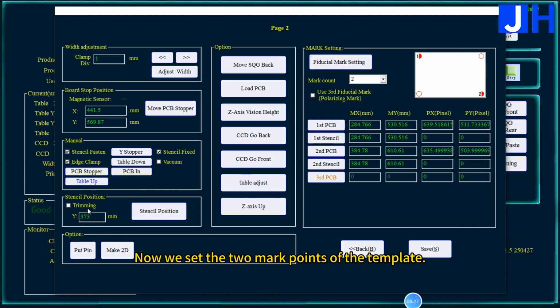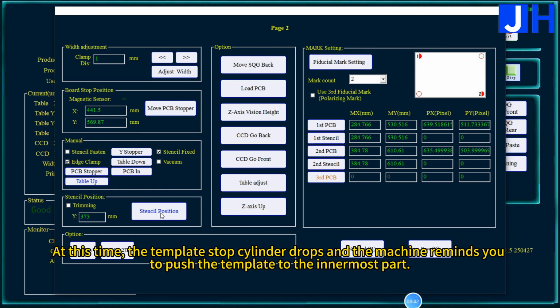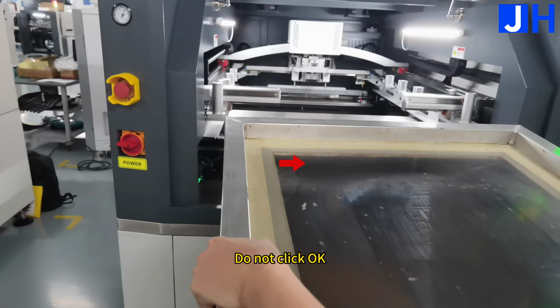Now we have set the 2 mark points of the template, but we don't have the template installed. Let's install the fixed template first. Click to unlock the template. After unlocking, then click on the location of the template. At this time, the template stop cylinder drops and the machine reminds you to push the template to the innermost part. Do not click OK.